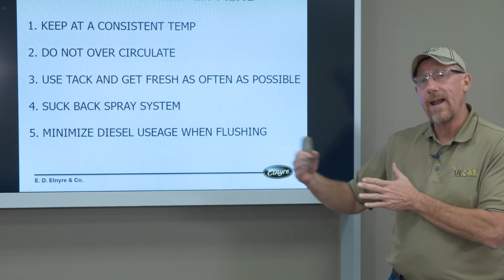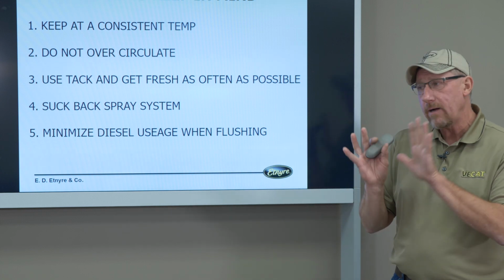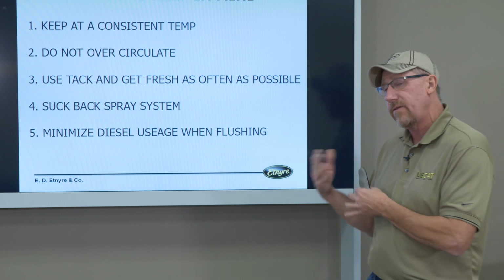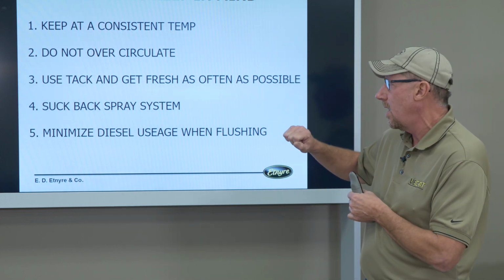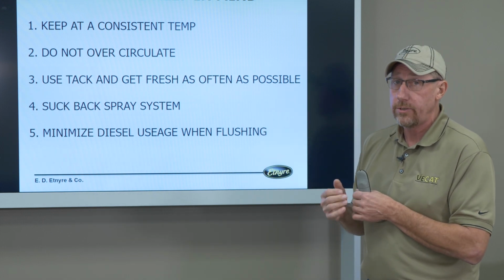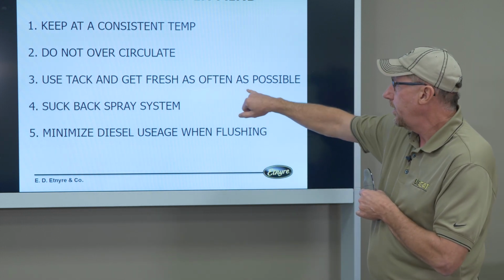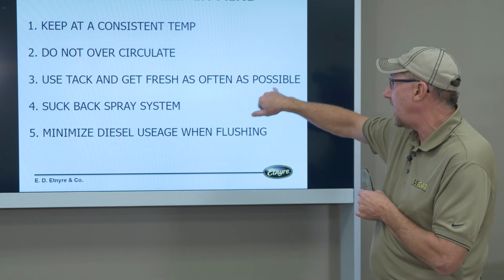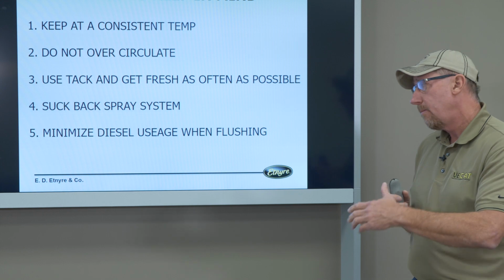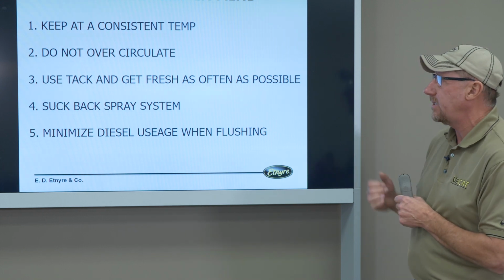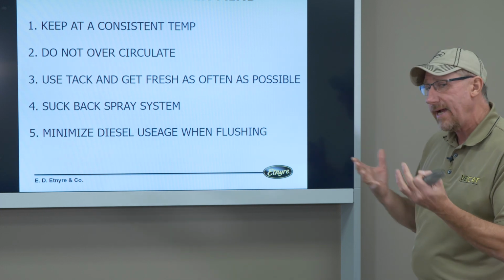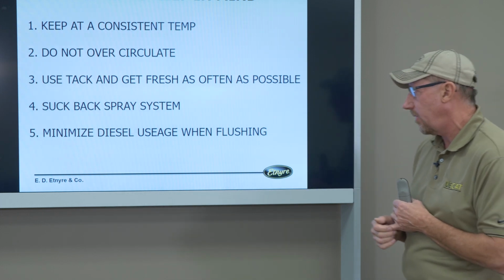So if you got to wait an hour or more, suck the system back, leave it in the tank, and shut your pump off. It's not going to get hard in your pump. You don't have to flush it or go through any of those processes, but you just want to make sure we don't over circulate it, because what you'll be doing is shortening the shelf life. Use the tack up as often as you can. Get fresh, okay? So use that tack, get fresh from your supplier, bring it back out. The fresher the tack is, the better it'll work, because we don't want to push that timeline of when Mother Nature is going to win that battle and pull that stuff apart.